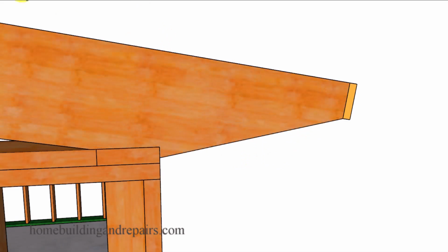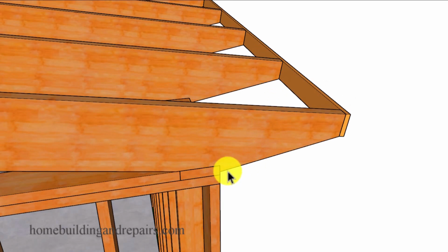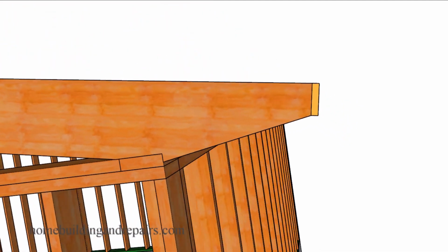And if that's the case, something like this might work a little better. Again, going from the bottom of the seat cut to the edge of what would be the fascia board measurement. And again, this could always be a little smaller. If you have 3.5 inch 1x4, you can always have this line come up to maybe 3.25 inches if that's going to work for you.